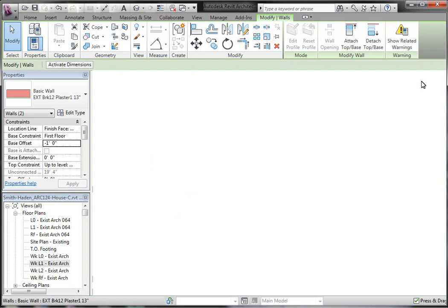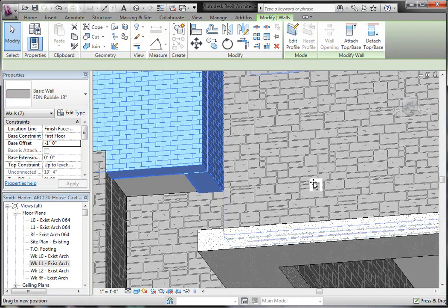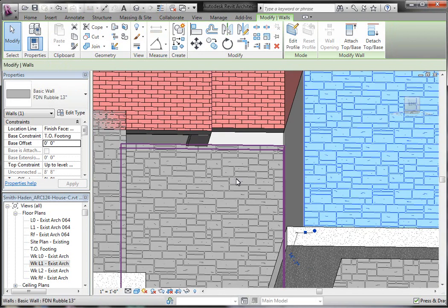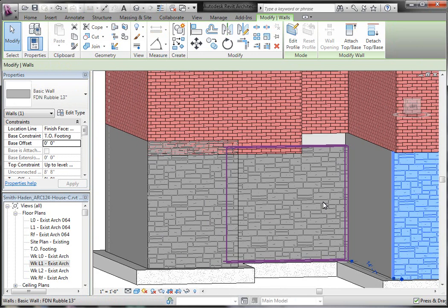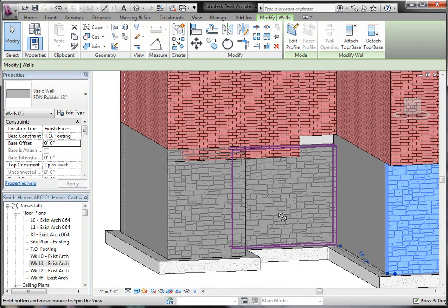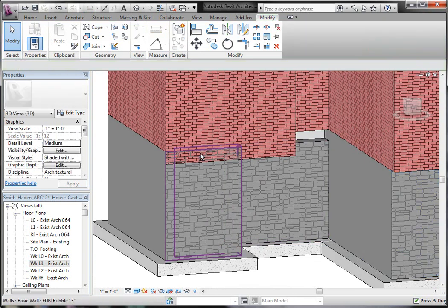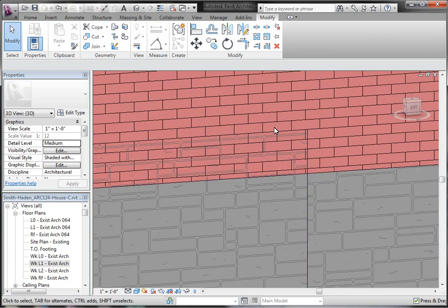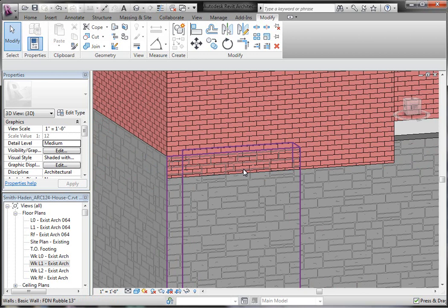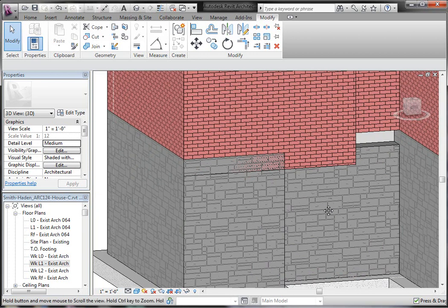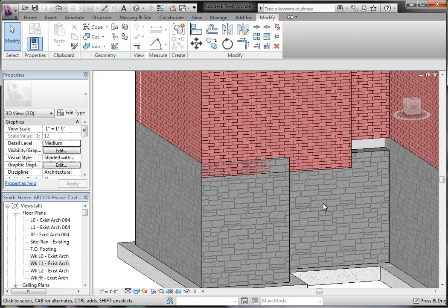But now let's look in 3D here a little more closely. I've actually got two walls that overlap just like what the message was telling me. And whenever you have two surfaces that are shared by the same plane, or a plane that is shared by two surfaces, you see kind of a little bit of cross imaging there, almost like it dances or shimmers on top of each other. So the way we fix this, and this little trick, is we need to join geometry, and because we're joining wall to wall, whichever wall I pick first is the one that dominates the overlap.